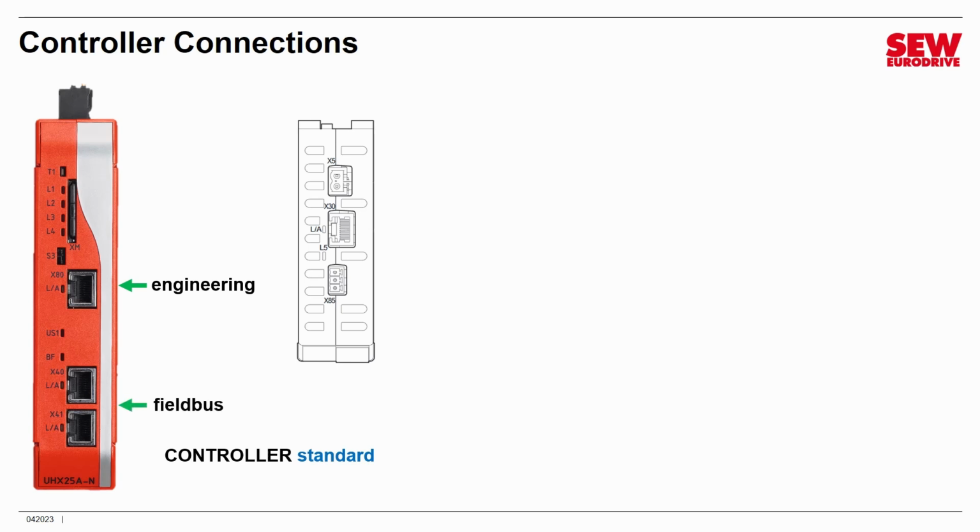There's also a pair of field bus connections. There's a 24-volt connection on top for its electronics. There is a single EtherCAT S-Bus Plus interface. The reason there's only one is because the controller is the master, so it's kind of the beginning of the chain. There's also a connector that supports what's called CAN. CAN is an industrial network used in certain things. As far as I know, we really don't do anything with this at this time, but we do have it in here. I'm not sure why, but it is there, so that's just what the connector is.